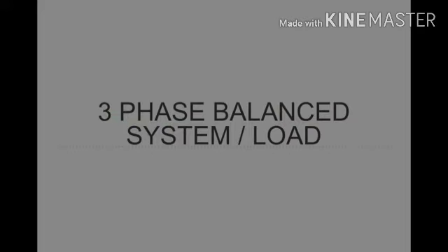When we talk about a three-phase balanced or three-phase unbalanced system, we must first know a very basic thing. That is, it is not the source that decides if a system is balanced or unbalanced, until the winding of the source generator is placed wrongly, which is a very rare case. It is the load which decides if a system is balanced or unbalanced.